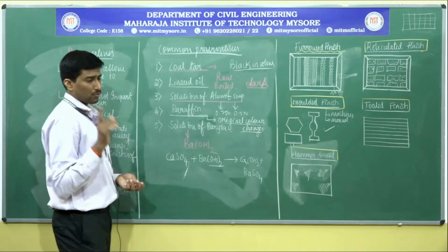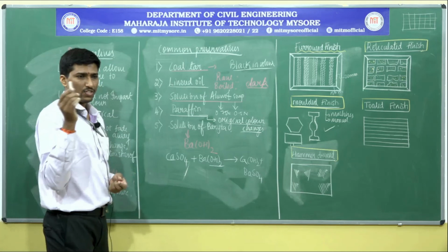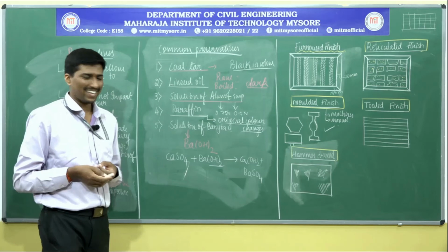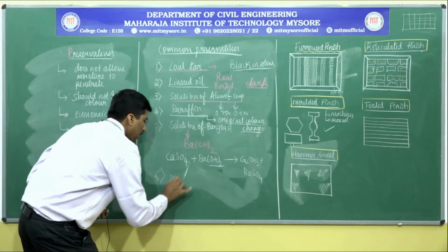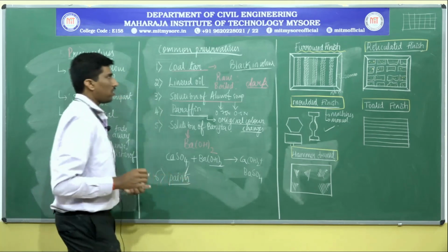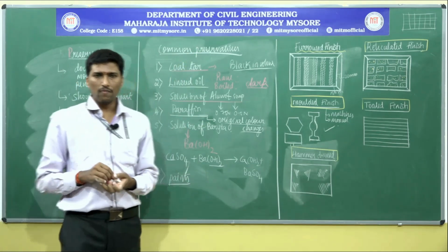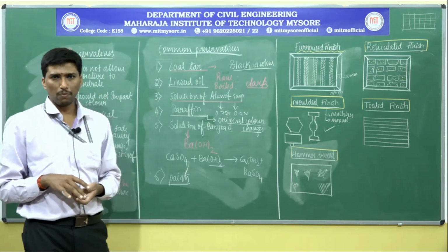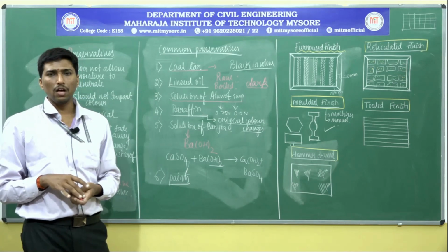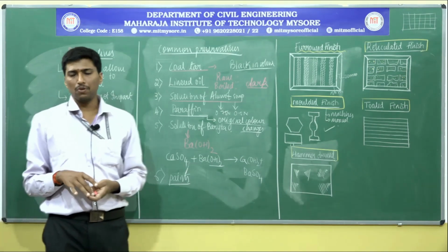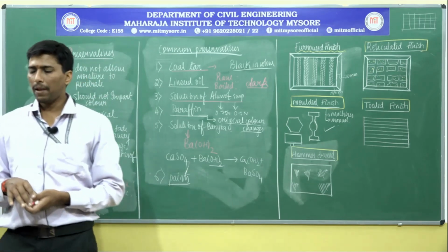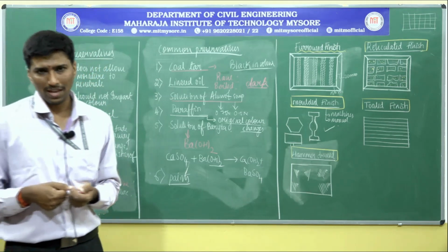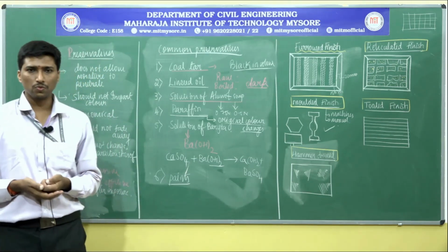Another important thing I forgot to tell: whichever finishing process is completed in the construction, we go for painting. So obviously, paints are also utilized for the preservation of the stones, where a color coating is applied gradually. It mainly protects the stone from moisture penetration as well as from atmospheric or chemical impurities. It is to be applied with the aid of pressure if deep penetration is required for the complete preservation of the stones.